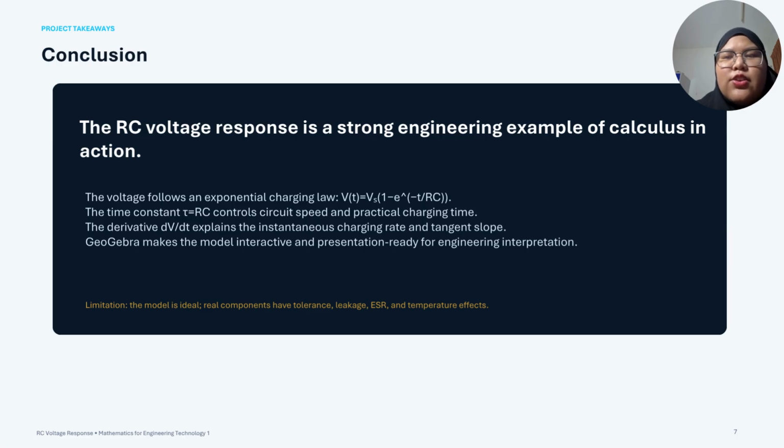And finally, it should be noted that this model is ideal. In real circuits, component tolerance, leakage currents, equivalent series resistance, and temperature effects can cause deviation from the theoretical response.